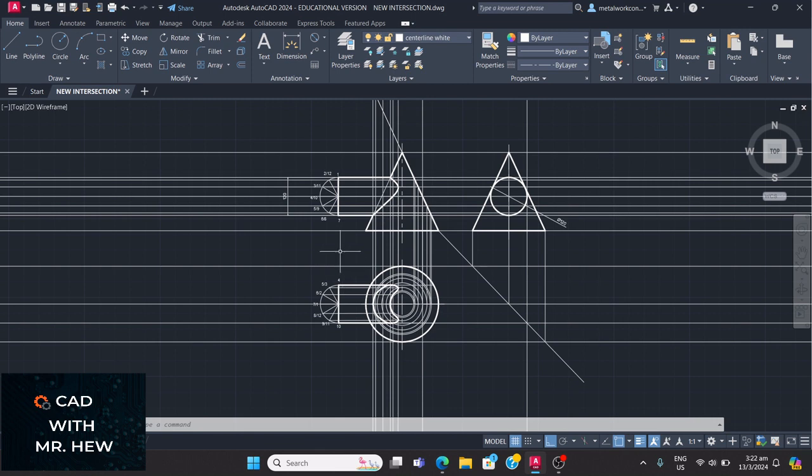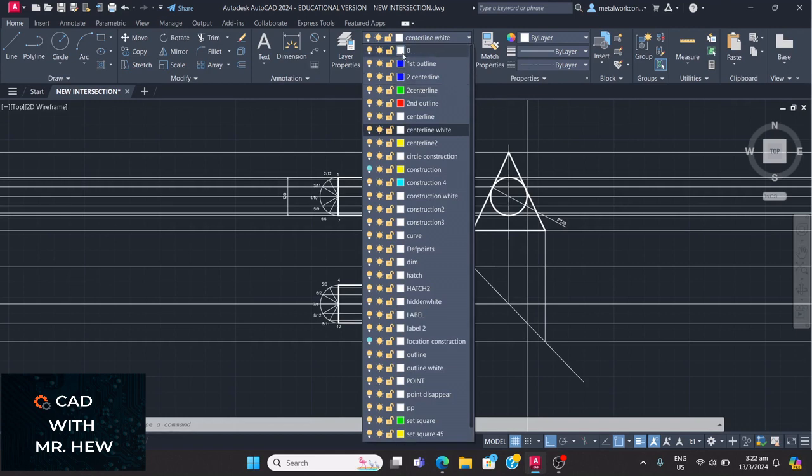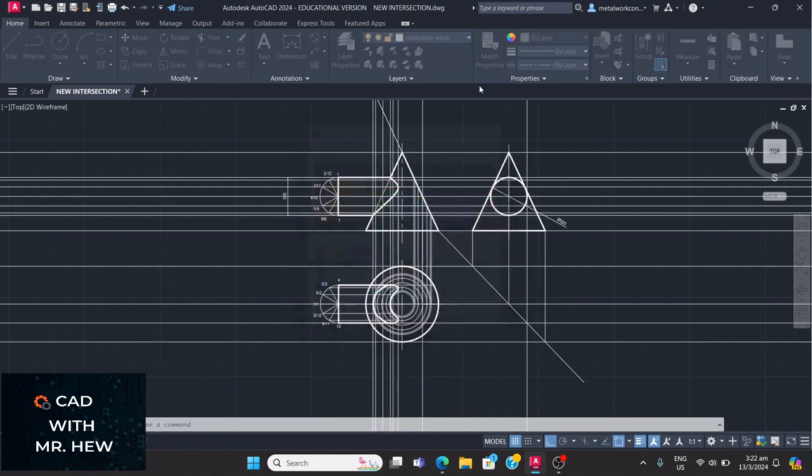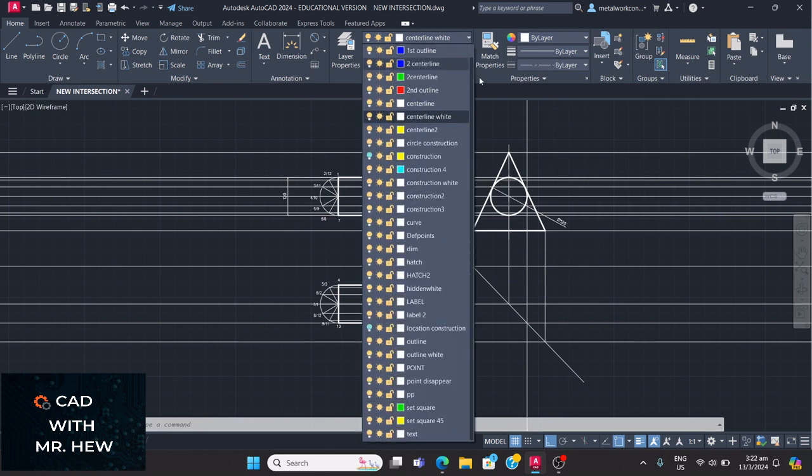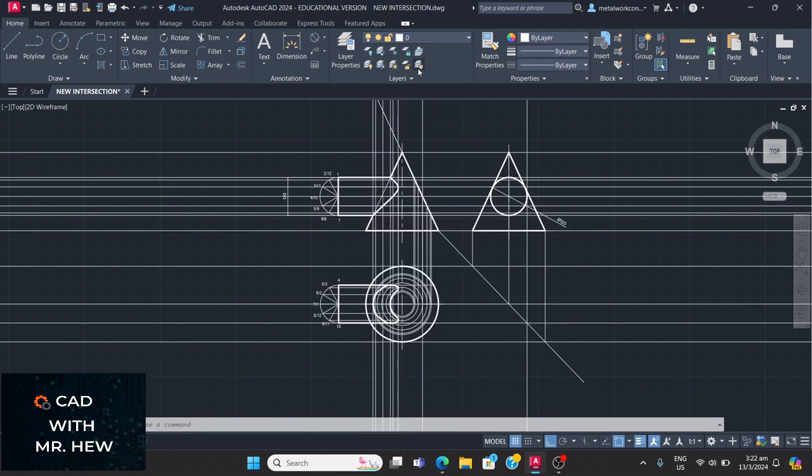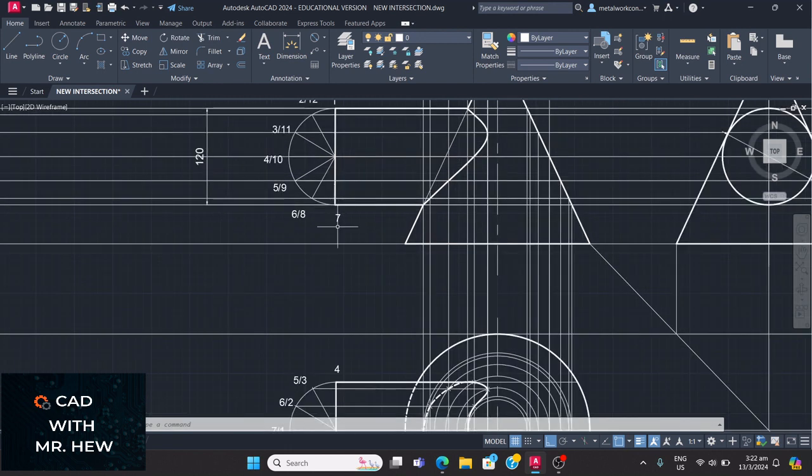What we're gonna do is we can draw a construction line. So I'm gonna change this layer to a construction line layer, which I use as the default layer in AutoCAD, 0. It would be a better practice to make a layer called construction rather than using the 0 layer. But anyway, maybe the next time I'll make another layer specific for the construction line. So what I can do, I can drop a perpendicular here. This will be the last point, right? This will just be construction.